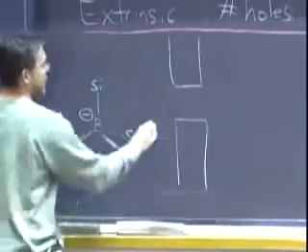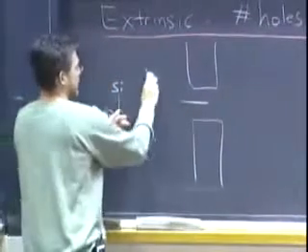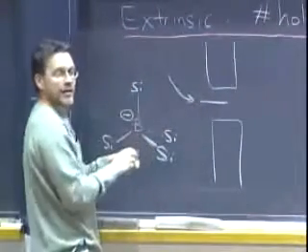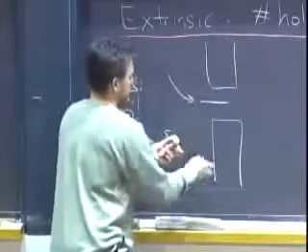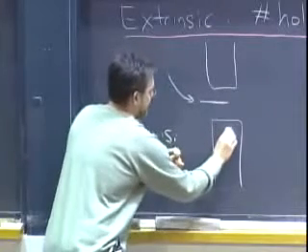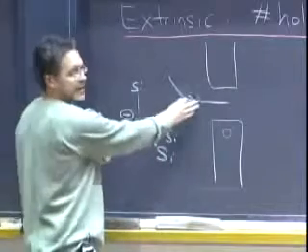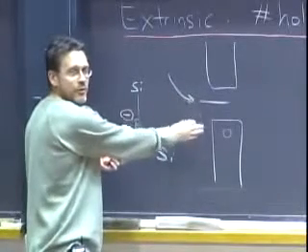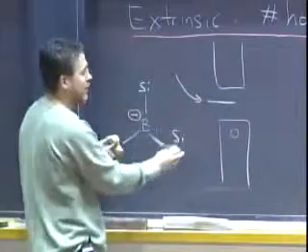You have bands, but then you have slipped in there a little orbital from the boron, a little electronic state here, intermediate between the valence band and the conduction band. So you have to choose your impurity correctly so that it has the right energy with respect to the valence band and the conduction band in order for the process that you want to occur.